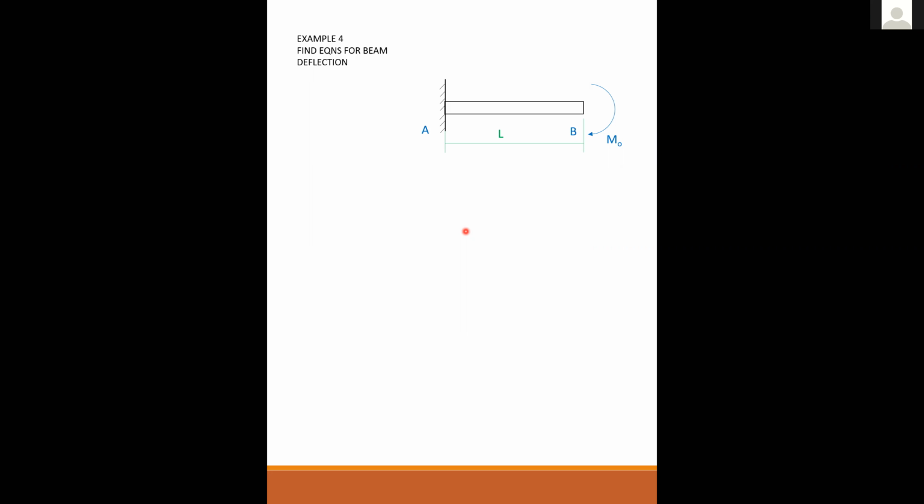One way to do it is to put the uniform load right on the beam along with this end moment. You have both of them on the beam. And then you just solve for your reactions with both loads. Once you have your reactions, you make a cut point and you solve for your internal moment as a function of W, the uniform load, and as a function of M naught. You'll have both terms in that summation of the moments. And then once you have that, you go through these examples exactly the same way that I did.